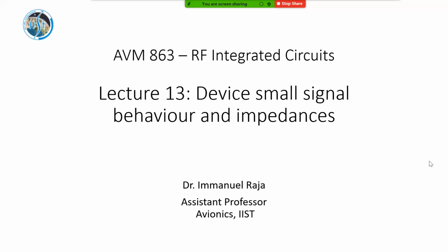So now, as we start looking at a low noise amplifier design, it is important for us to get ourselves familiarized with the devices that we are going to work with. In a typical microwave circuits course, there are different devices that are typically used. You'll definitely have some types of FETs, but mostly you'll be looking at silicon germanium bipolar devices, or gallium arsenide FETs, or gallium arsenide transistors. You'll also be looking at some HBT transistors or HEMT transistors, different types of transistors, right?